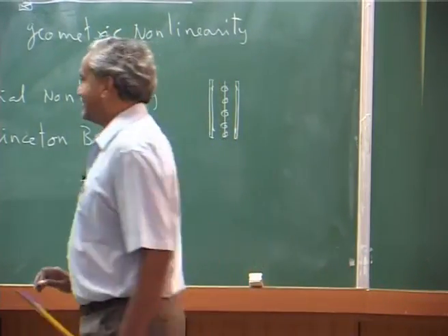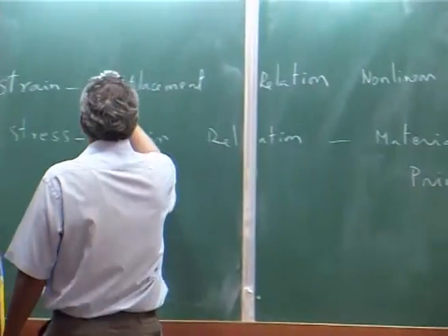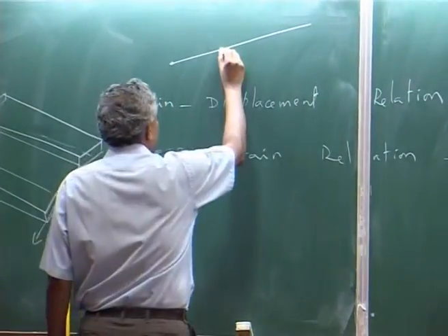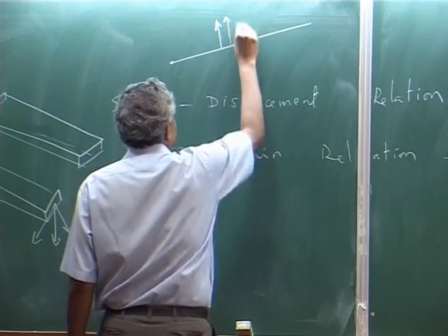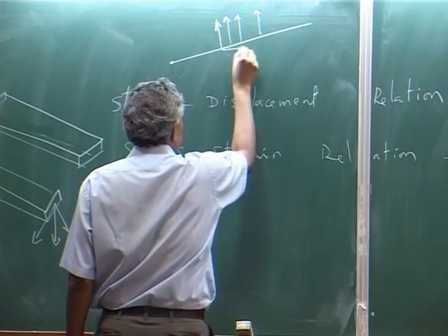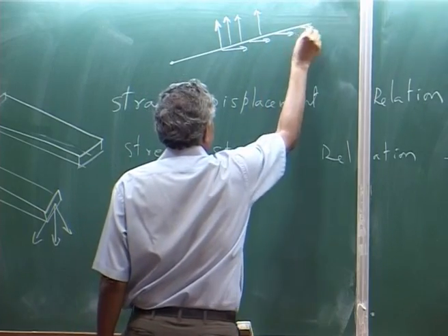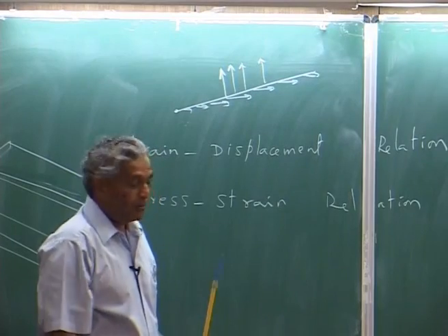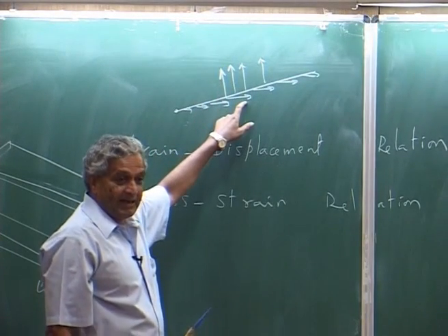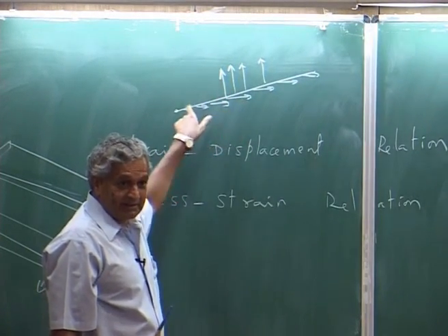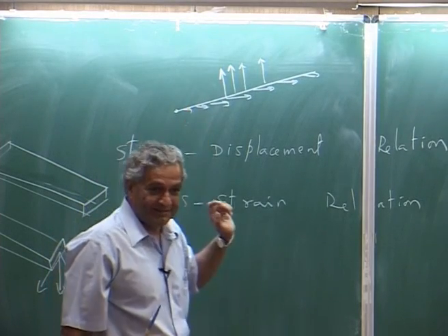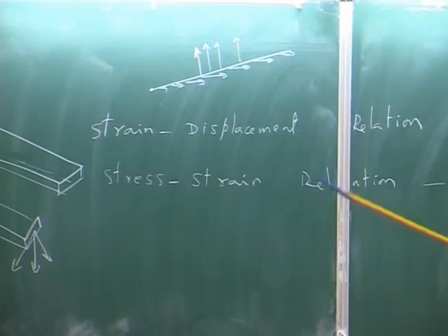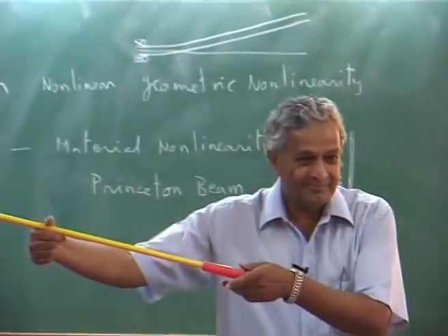It is not so here, that is what you have to know, because if you take this beam, your lift force is here, okay, and CF is here. Actually, the maximum bending moment is not at the root. Okay, you can have zero bending moment. That is why you can have a hinge and you still have an equilibrium. You understand?